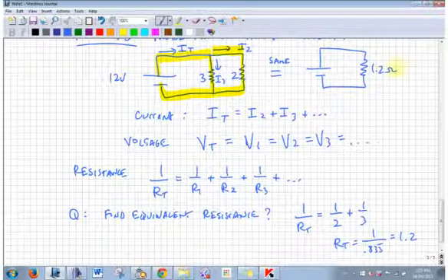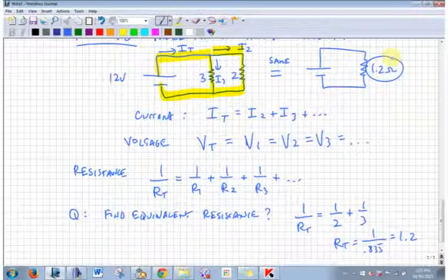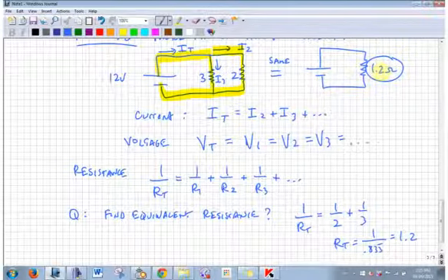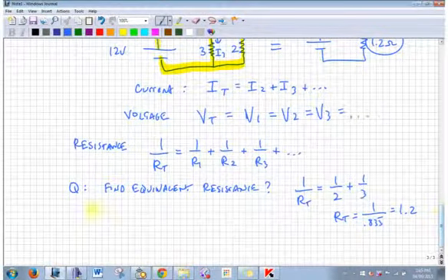That might kind of make sense. That's 3 ohms of resistance. The higher the number, the more resistance there is. That's 2 ohms of resistance. More is going to want to flow this way than that way. But if I've got 2 choices here, whenever you have 2 resistors in parallel, the equivalent always has to be a smaller number, right? Because there's 2 paths here. That's less resistance. So that's the same as 1.2 ohms in series. If that doesn't make sense, don't worry about it.